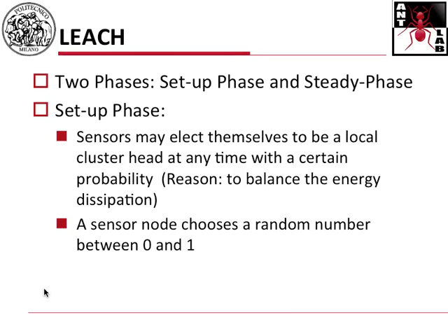So this LEACH thing goes on in 2 phases, which repeat periodically. The first phase is a setup phase, or clustering, or cluster definition phase, and the second one is a steady state phase, where clusters are defined. The setup phase is the phase to build up clusters.